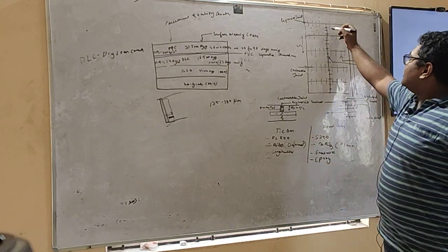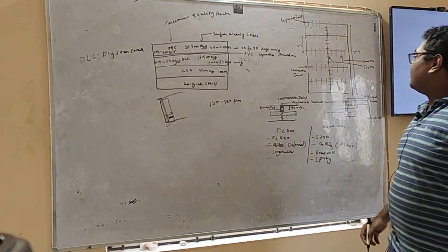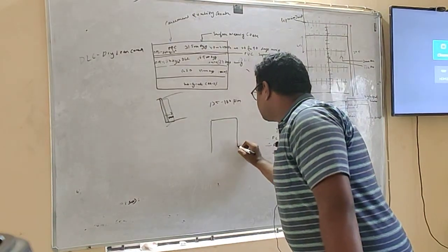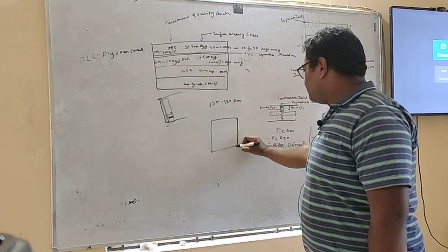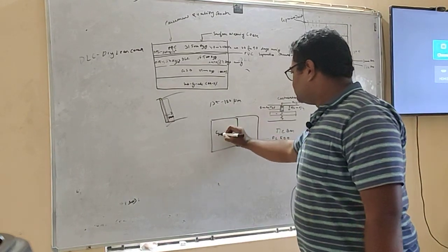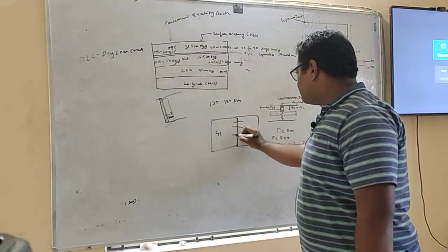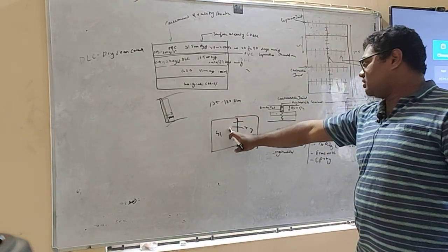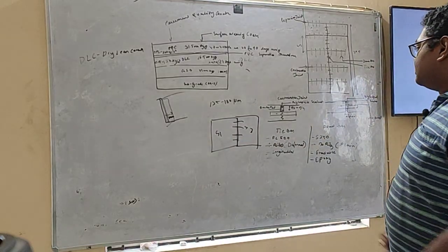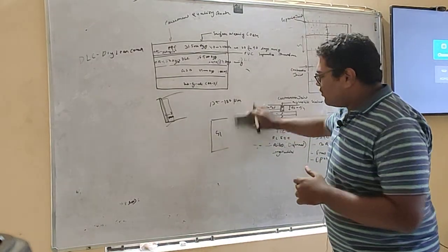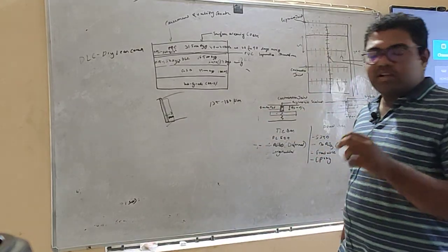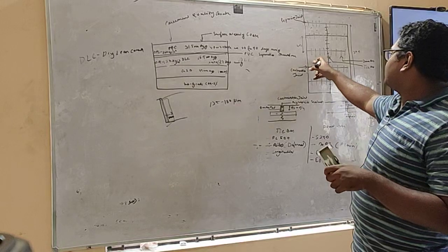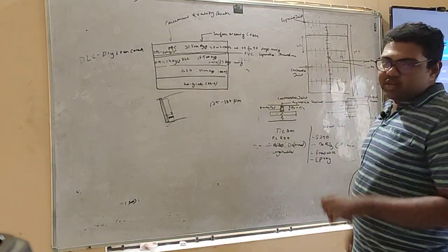Coming to tie bars, these are used to connect the different slabs of our rigid pavement. Our rigid pavement is laid down in slabs. These tie bars are usually given for better structural integrity of our rigid pavement. Another advantage associated with rigid pavement is that if one of our slabs gets damaged, we can remove that entire slab and put a new one in that place.